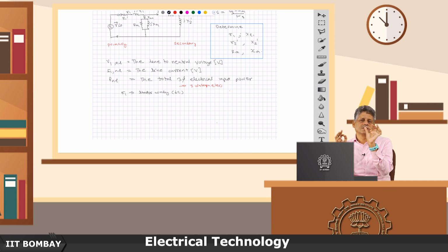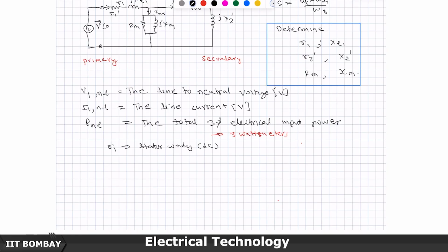Current usually remains within a skin depth, and skin depth is very small. So, it remains on the outer shell, and the current density decays exponentially as you go towards the center, and within 2 or 3 skin depths, most of the current will be packed. So, effectively the effective cross section area becomes smaller, and current density becomes larger. Therefore, AC resistance usually is higher than the DC resistance, and the higher the frequency, the higher is this effect, the lower the frequency, the lower is this effect.